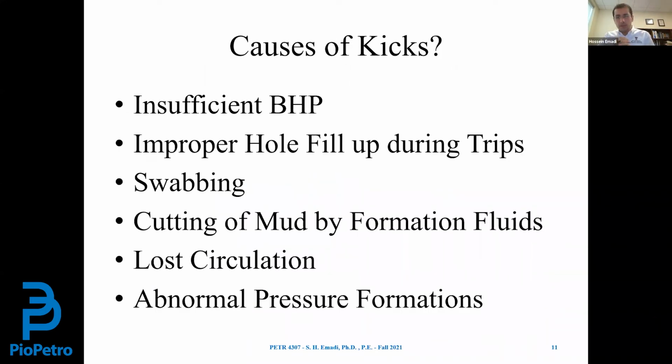So now we know about the importance of well control. What happens if we fail to manage a kick? And also we know about bottom pressure, the dynamic and static bottom pressure. We know about the mud window, fracture propagation pressure curve, pore pressure, the safe zone.